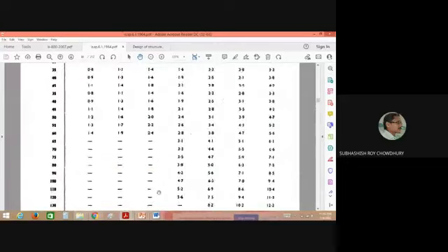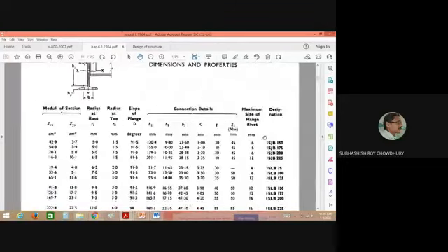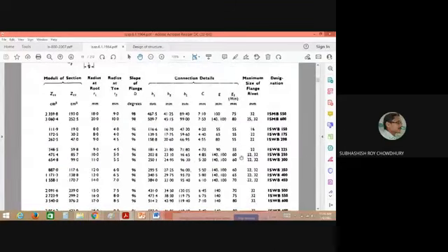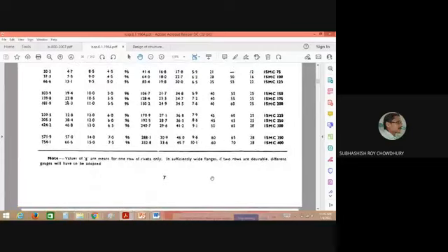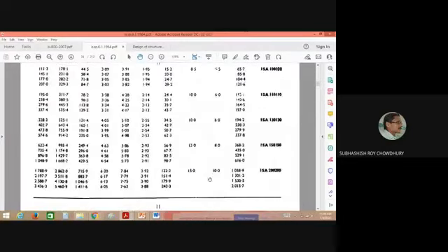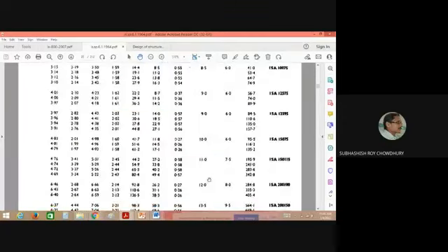So what are the different types of sections that are generally used? I am giving you the idea regarding this. So this is the angle section, I sections, then the angle section, etc. Sir, can you please give the sections which are commonly used? In case of beam sections, when you design the beam, you will use the ISMB sections. The medium beam sections you always use.